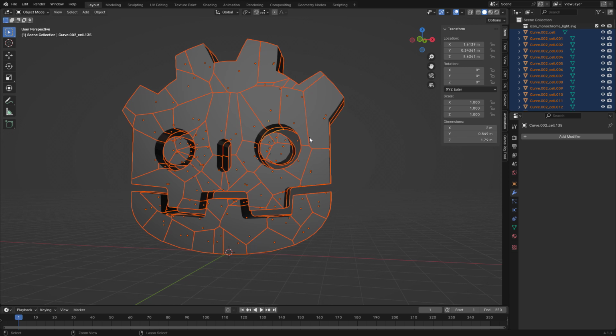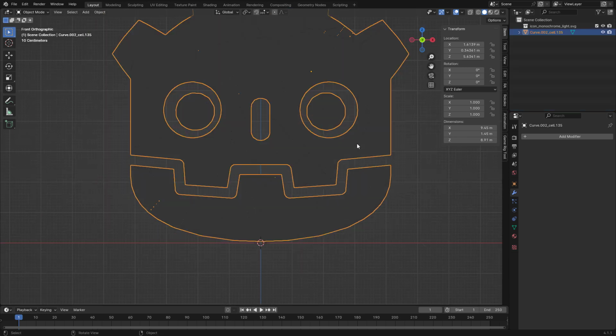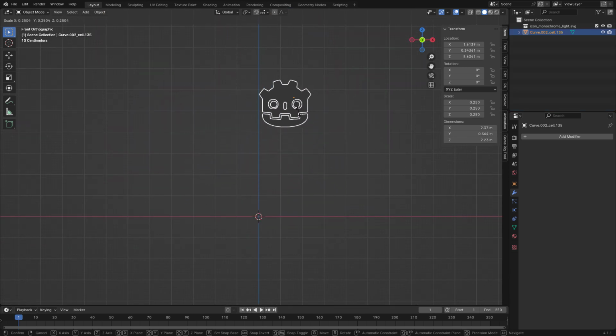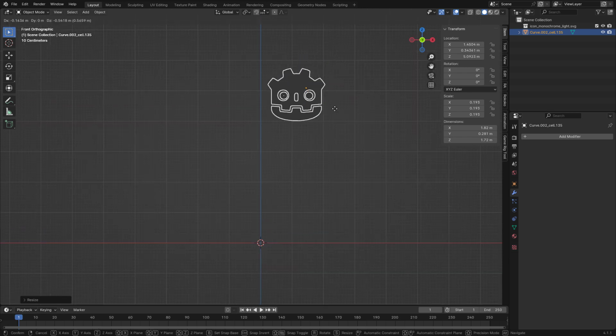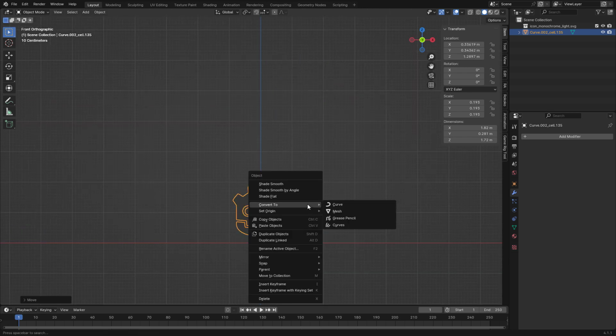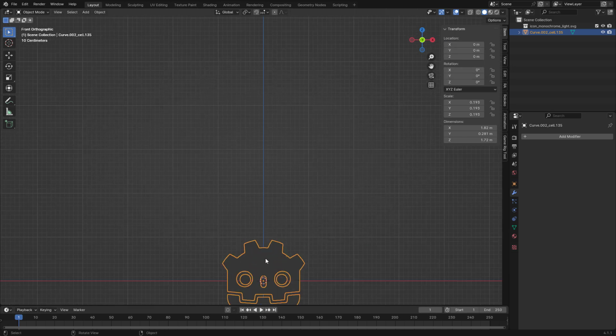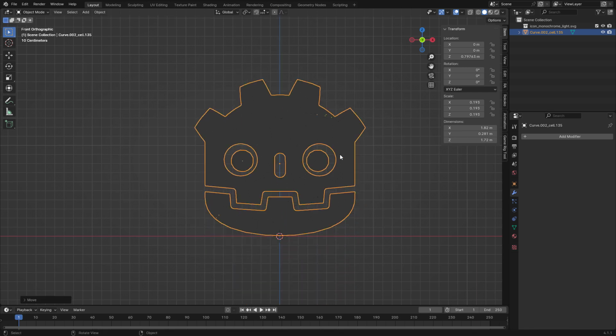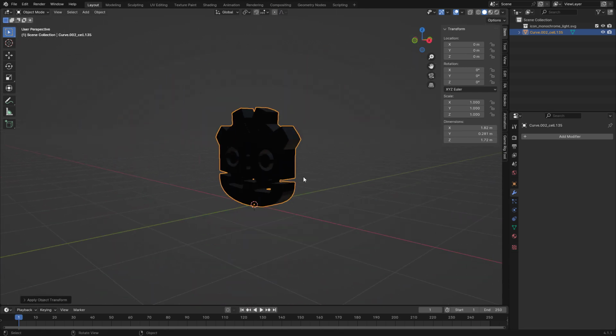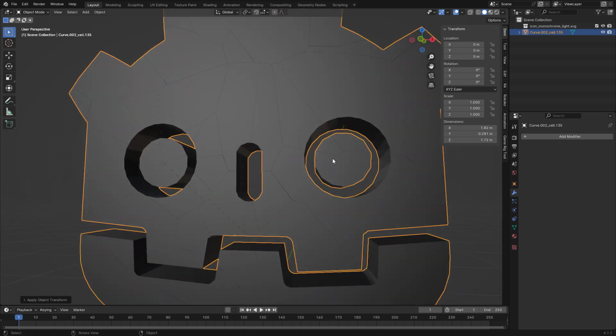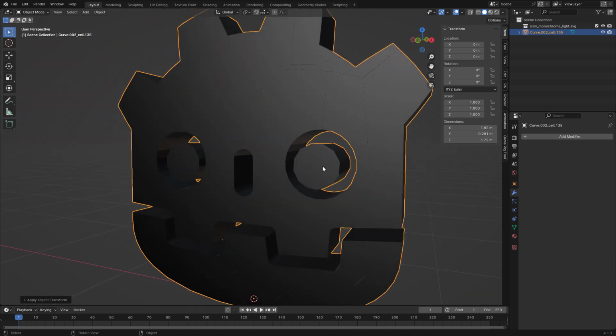Finally, I select all the objects and press Ctrl G to join them into one mesh. Now I'm going to reduce again to the original size to reduce also the spaces, and I recenter the mesh and put it right over the origin. I have the habit to always apply the transformations. Sometimes I forget it, and that causes horrible effects when exporting to Godot.